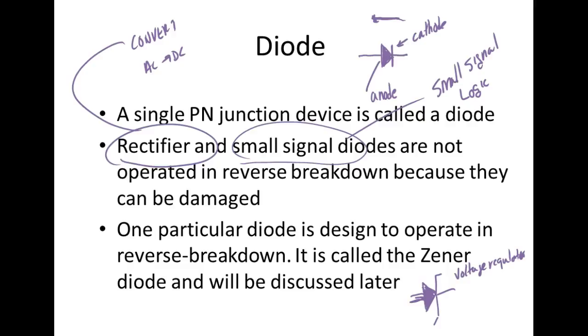Car batteries have almost none, right? So you have to be real careful with a car battery. But they all have source resistance. Go out to your car and put your voltmeter on the battery, don't crank the car, and turn the lights on. As soon as you turn the lights on, what's the output of the battery going to do? It's going to drop down some because of the internal resistance of the battery.